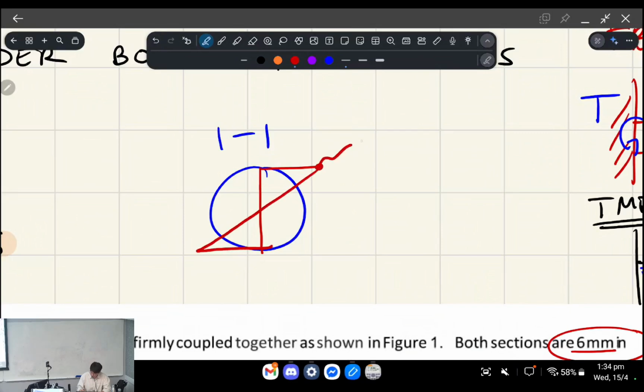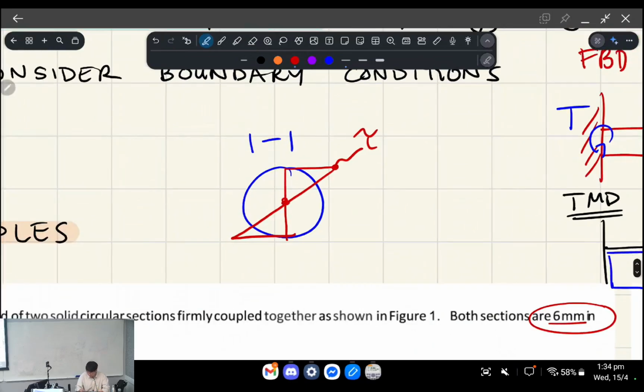Okay. And first, the outer edge is the first part that reaches yield because, as I mentioned before with my weird analogy, the outer skin part experiences the most shear stress when you're putting this whole thing into torsion. That's the torsion that you're putting. So that shear stress, we know that value has to be 100 MPa because that's the max it can experience before it yields, right?